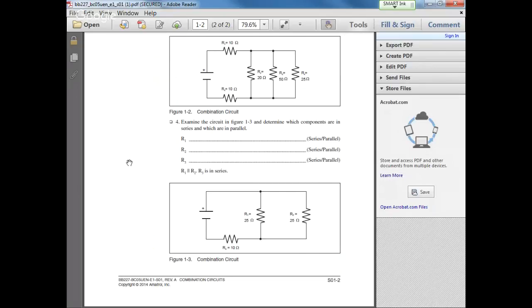So, all right. What again? Kirchhoff. When you're doing these problems, there's going to be double, triple, quadruple places where, if you mess up one calculation, the rest of it is wrong. So in order to check yourself, you can use Kirchhoff's law to add up the voltage drops, and then the current consumed across each resistor should equal the current total and the voltage total. Pretty much they're always going to give you one or the other. So you can add them up and make sure that it equals the source voltage or current, so you know you did your math right.